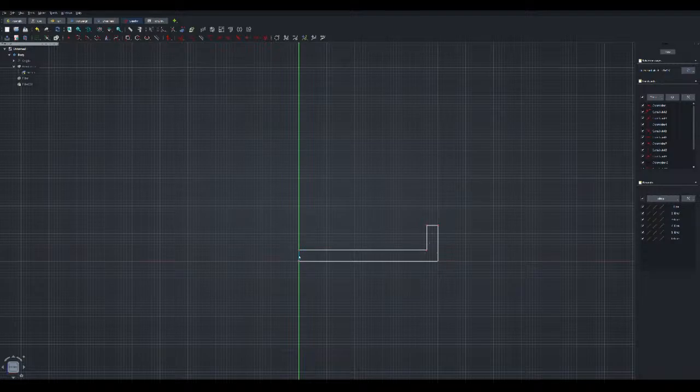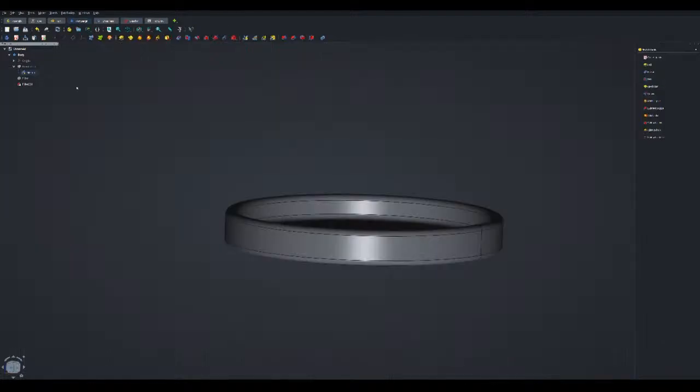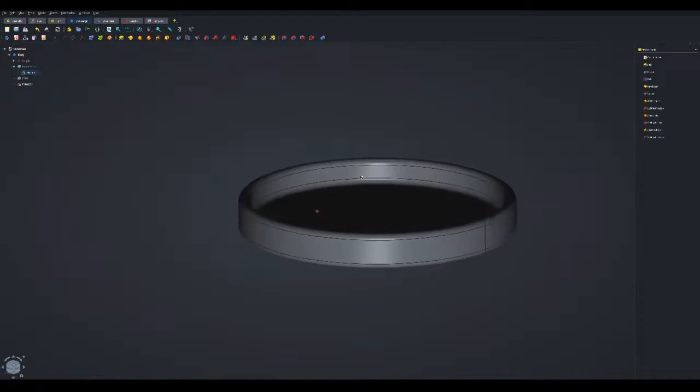I basically just eyeballed this while you were talking about things because I wanted to make sure I was trying to follow you, and got a shape that I found to be aesthetically pleasing for balance and the final part that I thought was going to be once it revolved. And after I left the sketch, I did have that 2-dimensional plane here hollowed out, and then I just came up and I hit revolve or revolution, and it gave me that part.